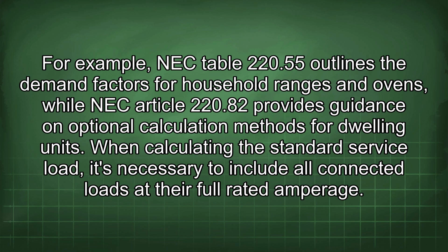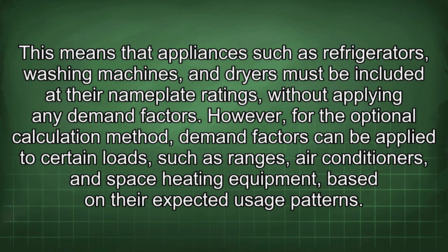When calculating the standard service load, it's necessary to include all connected loads at their full rated amperage. This means that appliances such as refrigerators, washing machines, and dryers must be included at their nameplate ratings without applying any demand factors. However, for the optional calculation method, demand factors can be applied to certain loads, such as ranges, air conditioners, and space heating equipment based on their expected usage patterns.